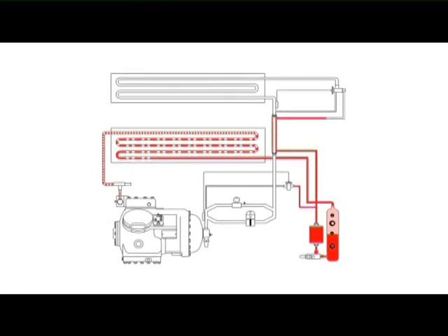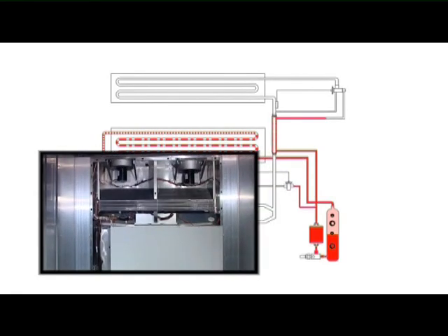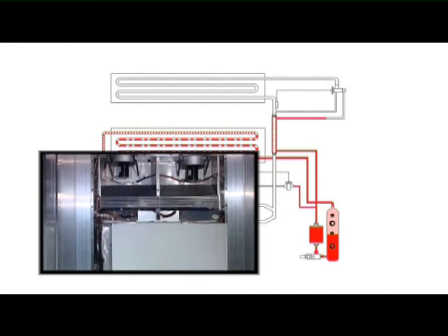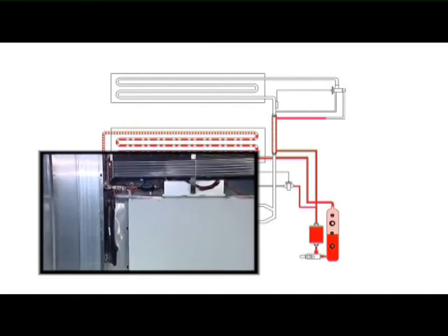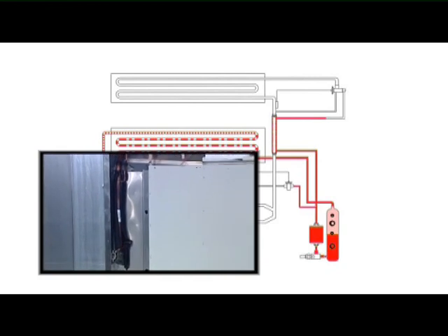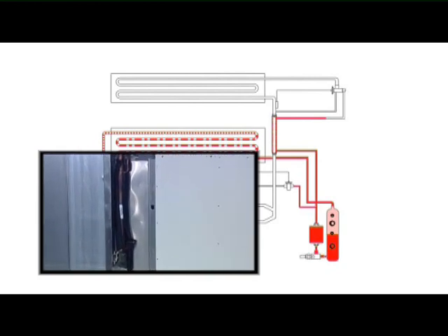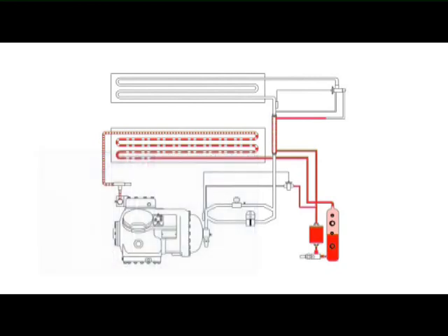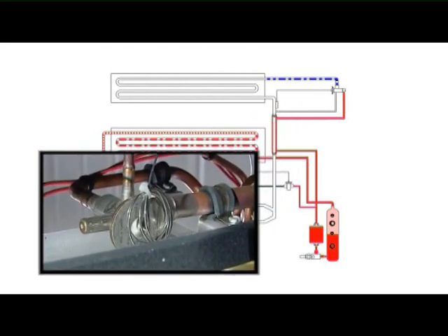The high pressure and high temperature refrigerant will reach the heat exchanger. In the heat exchanger, the high pressure and high temperature refrigerant transfer heat to the low pressure and low temperature vapor, returning to the compressor. This will improve the efficiency of the system. The refrigerant arrives at the thermostatic expansion valve TXV, which measures the amount of refrigerant entering the evaporator coil.